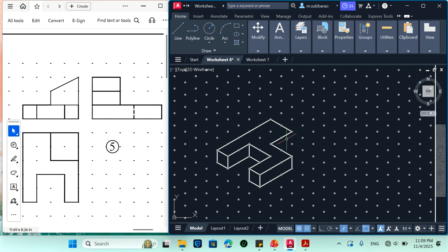So this is the H, and then again if you see what is there here, there is a projection, so we need to draw this projection. Then up to how much height? 10 mm height, if you see this. So 10 mm height, and then here it is 20 mm height, that we can see in the side view.